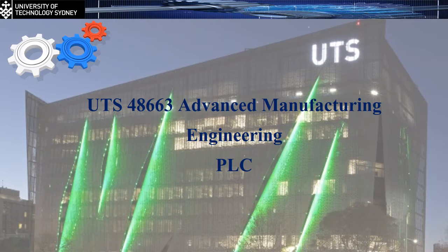So we have to divide the price of the cutting tool by the number of edges. For the grinding, we have to multiply the time required for grinding one edge by, you have to open the bracket, the labor cost plus the overhead cost for the grinding. This will be in dollars per hour for both. So you have to divide this by 60 to have it per minute. Okay, that's how to find the value of the CT.